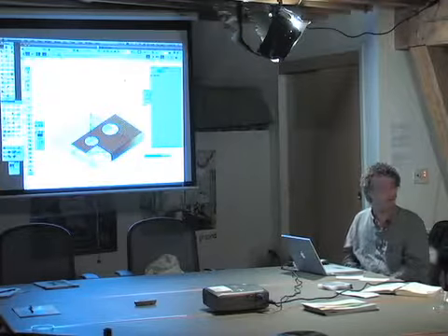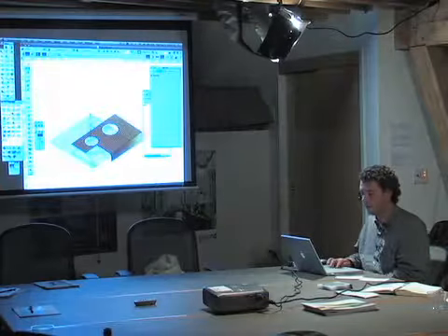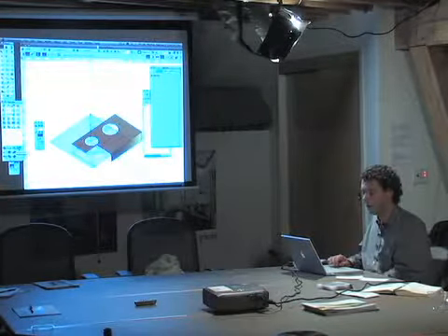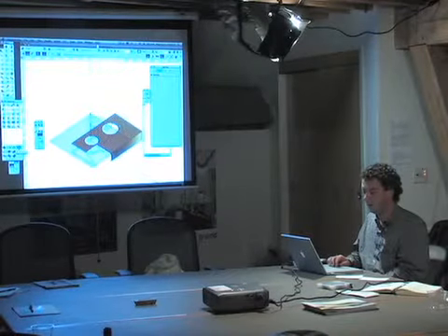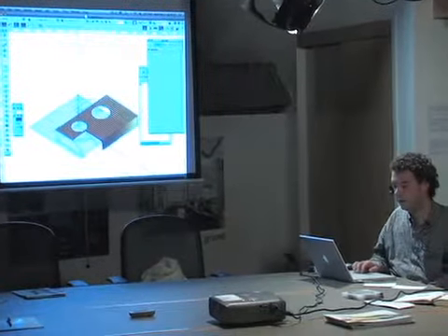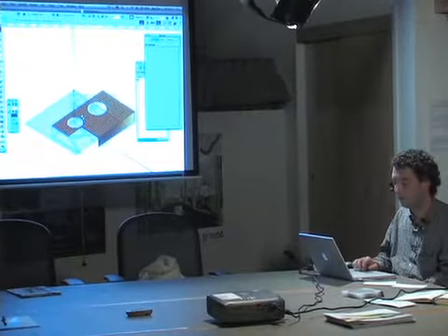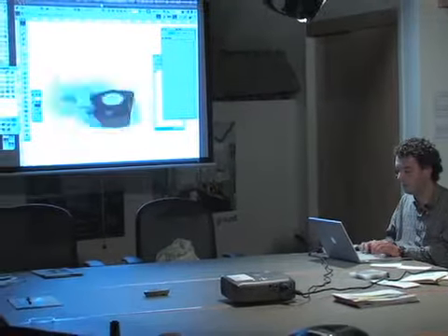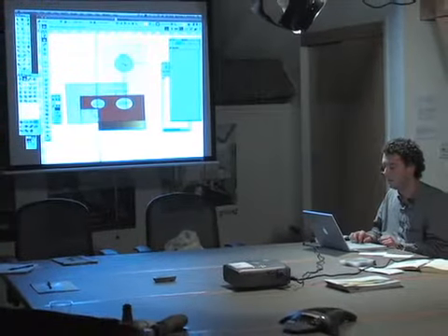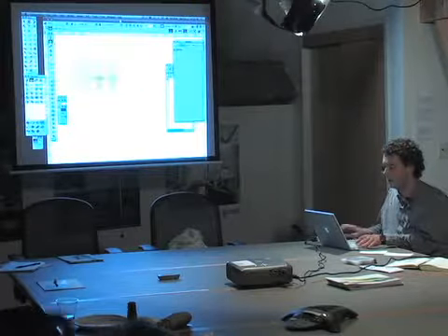So that extract face, was that a command? I didn't quite see where that came from. Yeah, I'm sorry, I should have shown you guys where this all comes from. It's in the 3D modeling set. I usually just pull it off here to the side as its own toolbar. And that has our rotate, I kept hitting Shift-C and was able to spin around the model. That activates that. Here's our working plane, and it's much easier to set a working plane to an object.